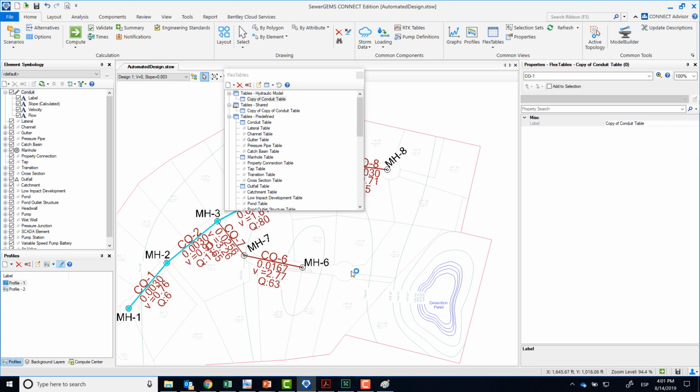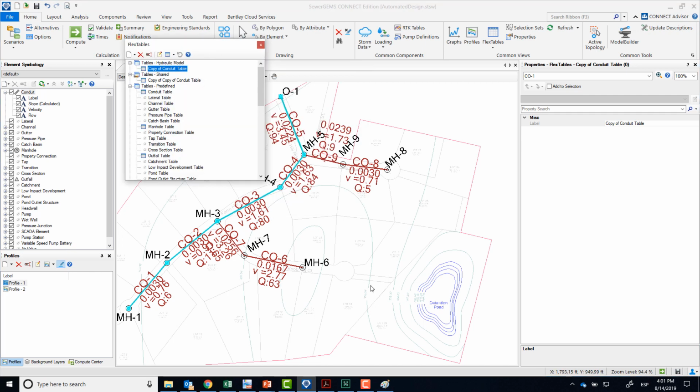Third question is, what other way could you have served the 4 homes on the other side of the drainage divide? You could have had them connect perhaps to the manhole 8 if they were connecting on the right side, but then going through people's properties, not as simple. Or you could have collected via gravity at a low point and then pumped to MH6 instead of individual grinder pumps at each home. And what would you prefer, the original invert elevations or the values that we got from the designs? And the solution here is a decision between how much it's going to cost to excavate versus the velocities.